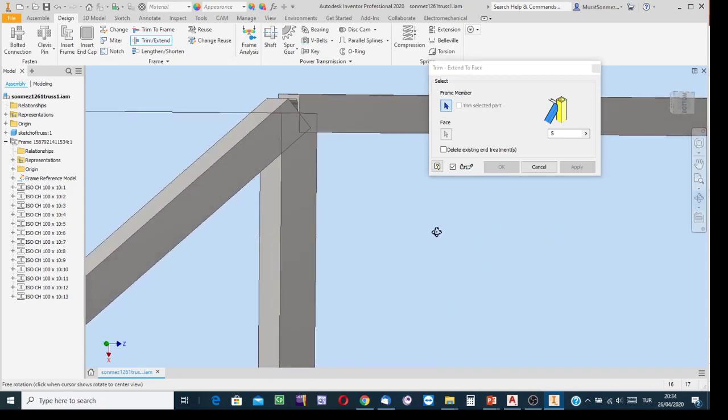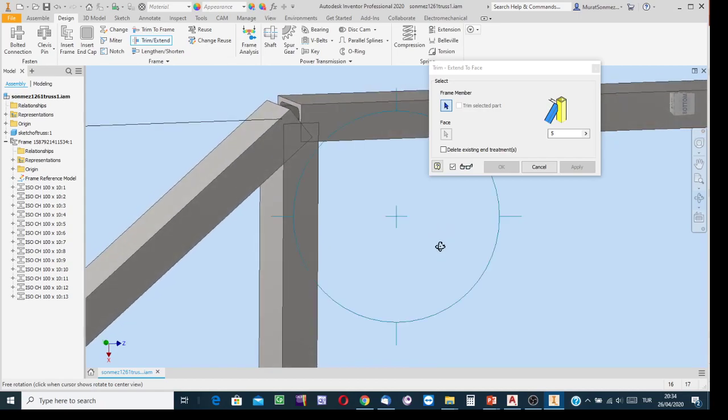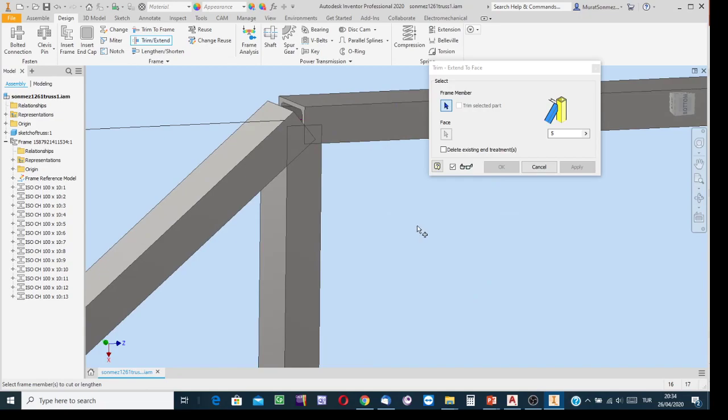to be able to indicate what I am doing, I tilted it to allow myself to see things three-dimensionally. And then see, blue, yellowish. Well, blue corresponds to the member that has an interference. Yellowish corresponds to the target surface. It is to say that after that surface, chop the rest. You see, after this flat surface of this vertical member, I have an interference. The rest of this member, after this limit, is interfering.